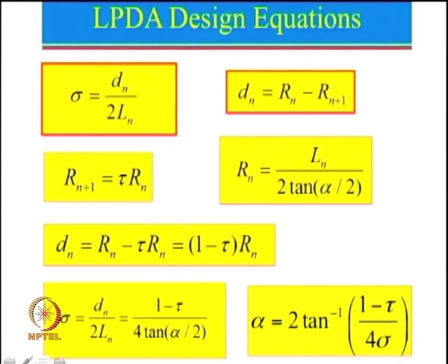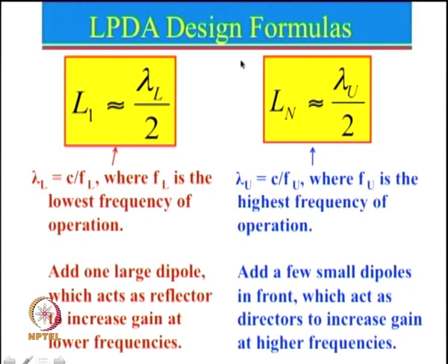Then comes the next part, and that is the lowest one here. For the lowest dipole, we again recommend that you add a few small dipoles in front, which will act as a director to increase gain.